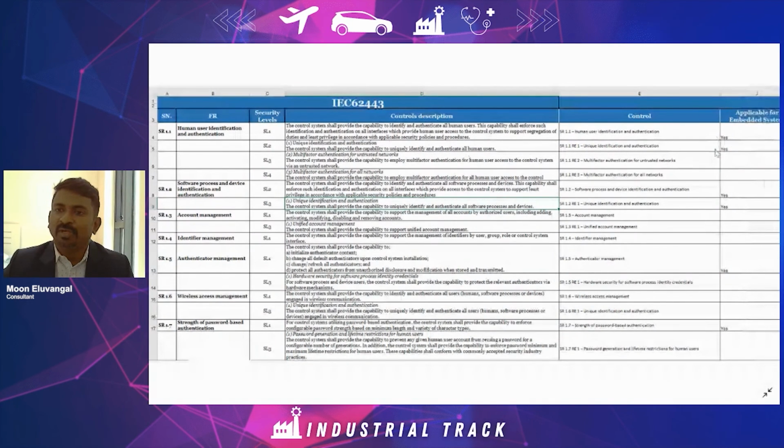One of the attacks I mentioned, Stuxnet, in which the program was changed in a PLC, all happened because of a lack of this type of control. If we have to meet a particular SIL, then the embedded devices used in that system have to be configured properly. Sometimes it happens that passwords are not configured or proper encryption is not used. So first, one important thing is configuration. Second, the device itself should have that capability. So the device vendors should look at this 3-3 standard also from a security assurance point of view. Most of the time I have seen the dash 4 standard being followed by most vendors, but I believe 3-3 is also very important. Only then can we achieve system level assurance, if the components used in that system have that compliance.